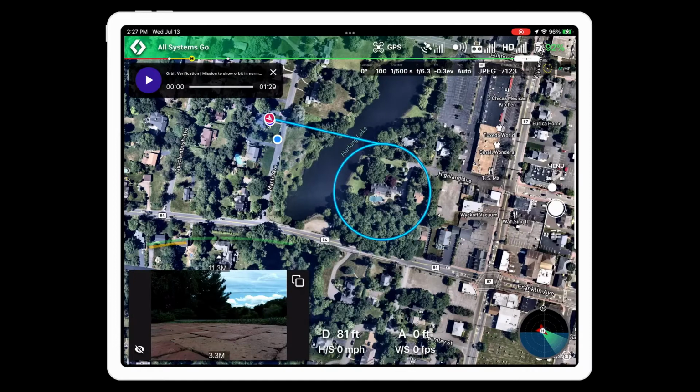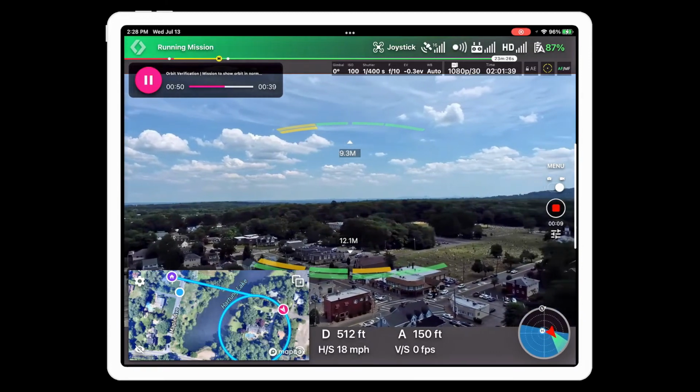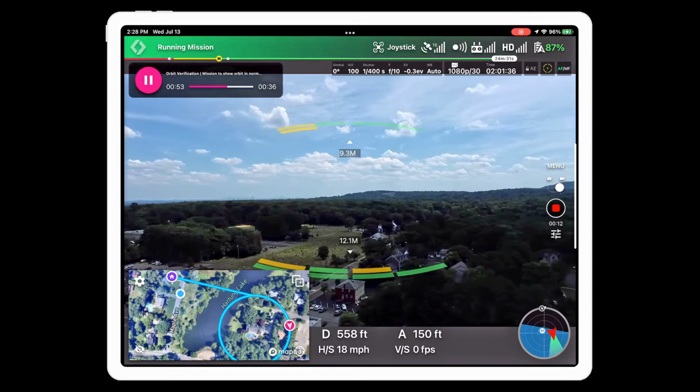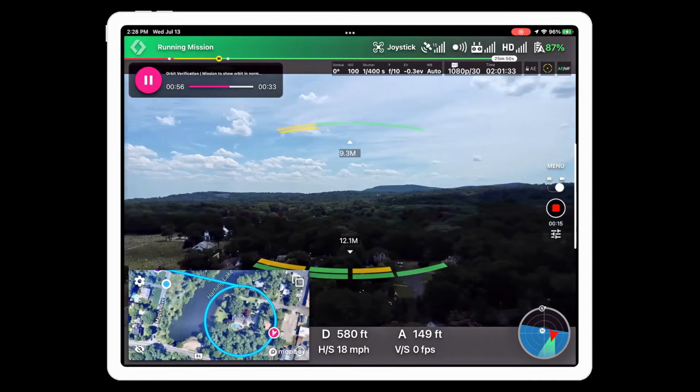At this point, Dronelink will open in the usual way. You just select the play button to kick off the mission. Once underway, however, you'll see the drone is facing forwards with the gimbal angle set to 0, instead of the camera pointing towards either the point of interest or, in the case of this orbit, towards the center.